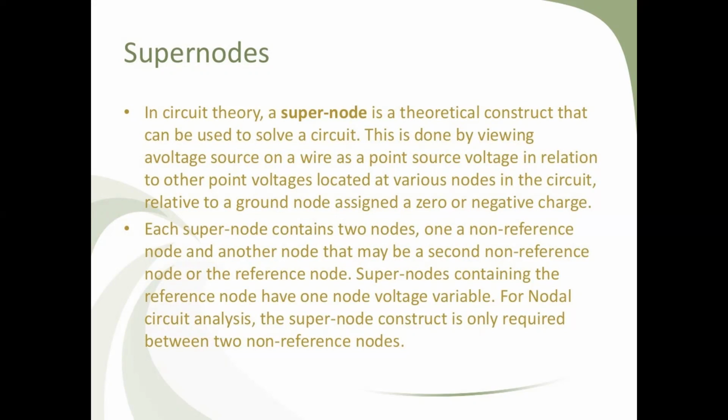Each supernode contains two nodes, one a non-reference node and another node that may be a second non-reference node or the reference node. Supernodes containing the reference node have one node voltage variable. For nodal circuit analysis, the supernode construct is only required between two non-reference nodes.